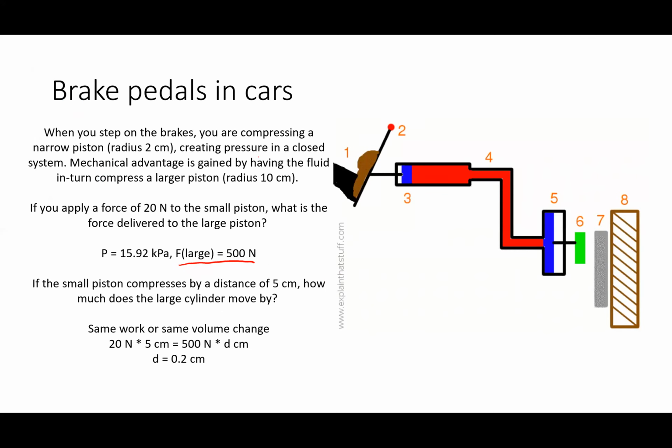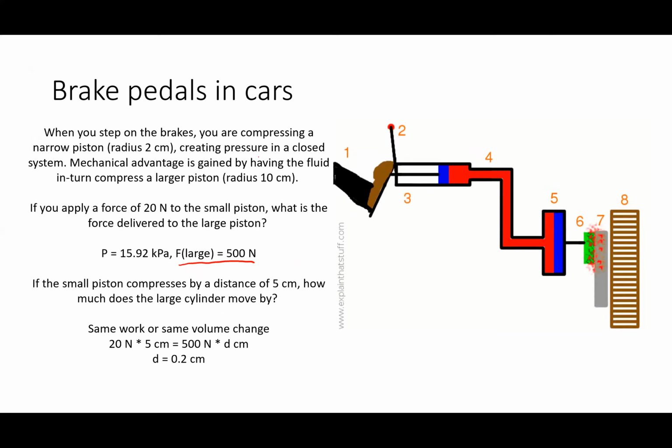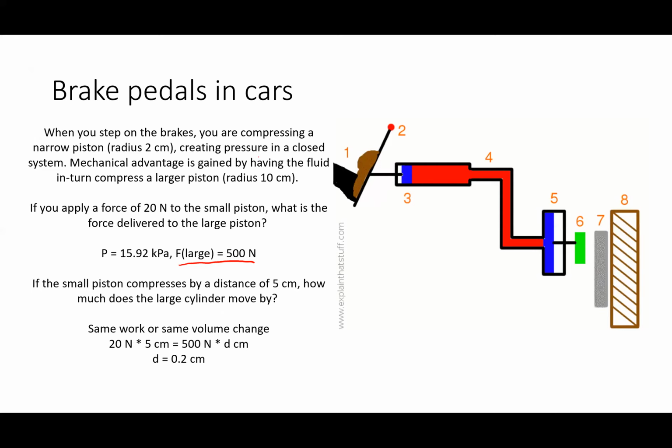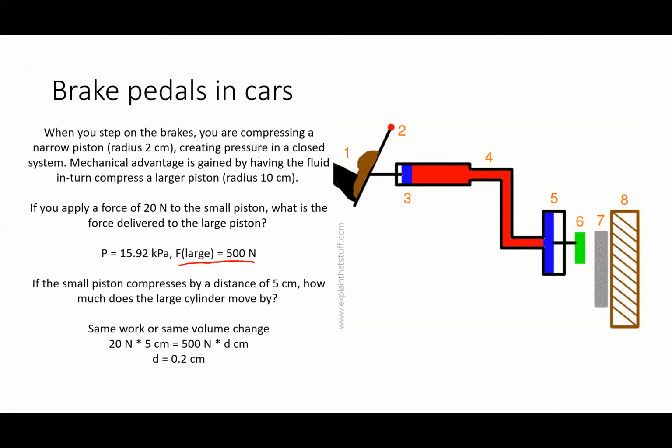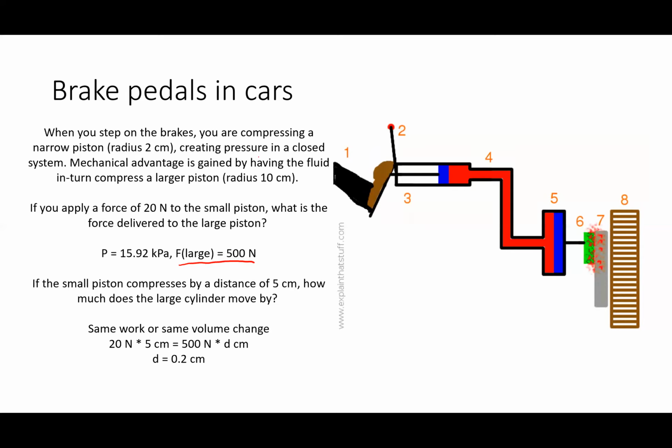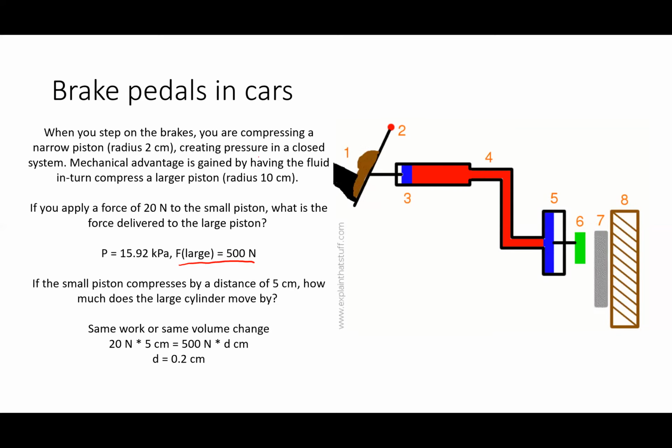So the brake disc only moves a few millimeters to act on the brakes. Meanwhile, your pedal moves several centimeters. So that multiplication of force comes with a decrease in distance to keep the work done the same. You're putting the same amount of energy into the system, but you're delivering a larger force. And that's how we get a mechanical advantage with hydraulics.